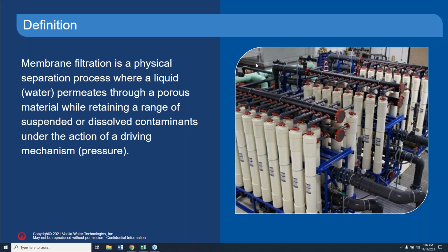And what it really means for those of you who want to work with or around them is that the UF plants can be very well automated. They have low operational labor requirements to do what they do. And depending on feed water quality, these systems do require periodic cleaning or backwashes, but they can go very long